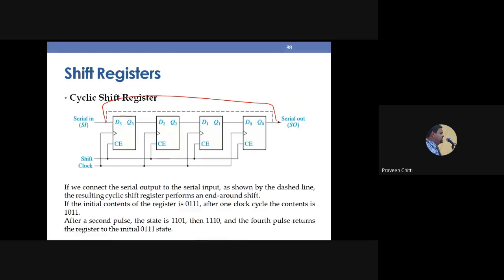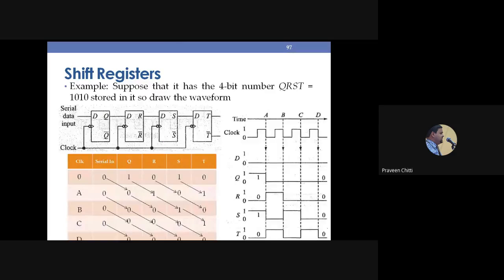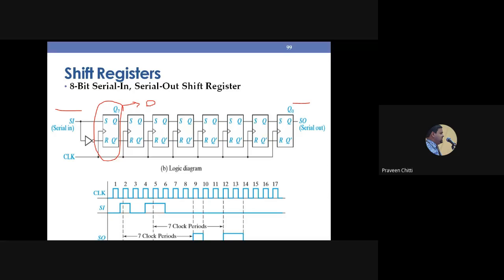So the same operation that I have explained here is applicable for this also. But the difference is we have used SR flip-flop. But effectively that SR flip-flop is used like a what? D flip-flop. And one important thing you should remember in all these counters and registers is that this flip-flop will be the LSB flip-flop, that is Q0, and this will be the MSB, that is Q7 if it is an 8-bit.